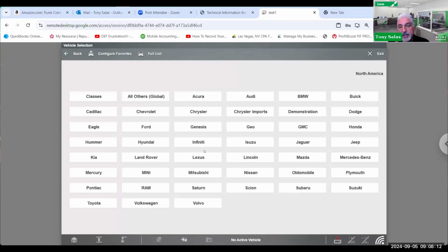when it comes to PIDs, when it comes to sensor specifications, it is not as elaborate as it used to be. And they used to have some, like Ford, for example, would have some diagnostics that they actually would tell you to follow. So it's all out there, and it kind of frustrated me because we should have at least some kind of chart that tells you step by step. Now there are symptom charts, okay? Ford has symptom charts, so if you got a no crank, no start, what they want you to do, and various other things that you can look at.